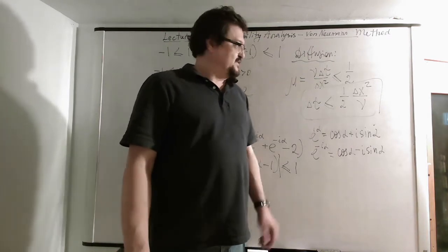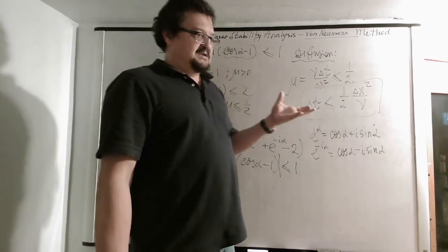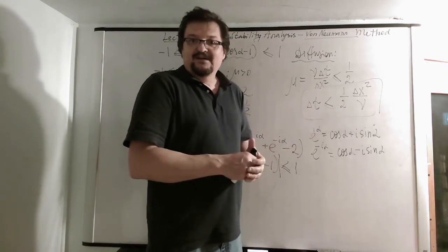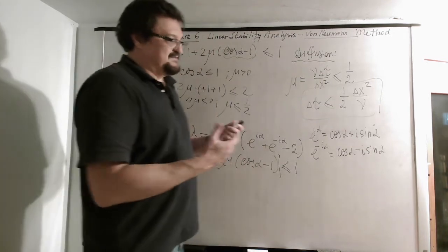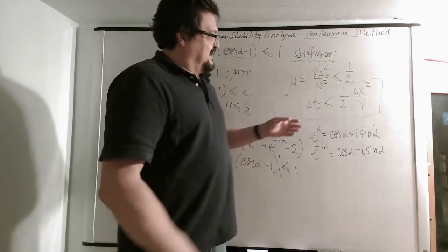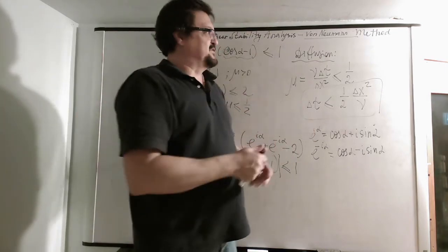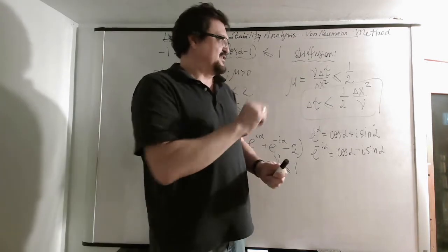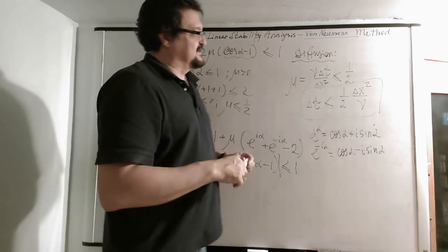That's not good news. That's relatively bad news, because you basically increase your resolution, and then your time step should decrease even more than your resolution. So that's not good. You will have to simulate the same time. You need to make your time steps 4 times smaller if you halve your grid spacing.